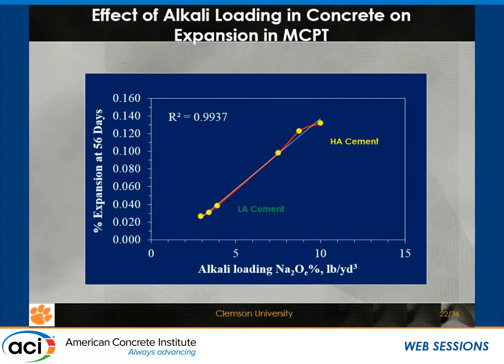We all know that the alkali loading makes a big difference. So clearly there is a linear trend there in terms of alkali loading that supersedes any individual influences of either cement content or water cement ratio. All of those things can be expressed in terms of the total alkali loading. And these are the low and the high alkali cements, and they match up quite well.